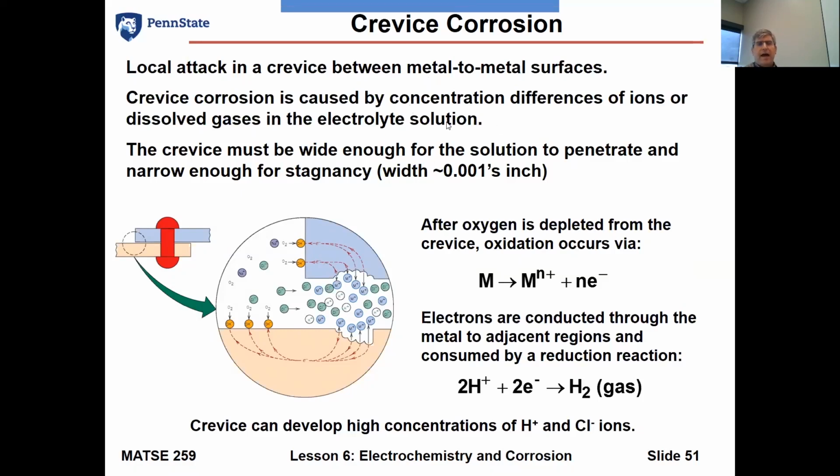And what makes crevice corrosion a little different from galvanic and uniform corrosion is that crevice corrosion is more localized. It occurs in the gap, or crevice, between two metals that are held in almost intimate contact. And with that, as you start thinking about capillary forces, you can draw in a small amount of liquid in there, but that liquid becomes trapped.